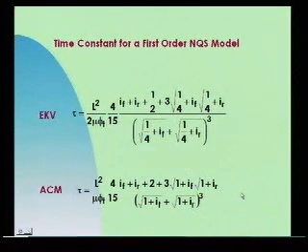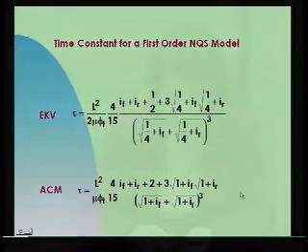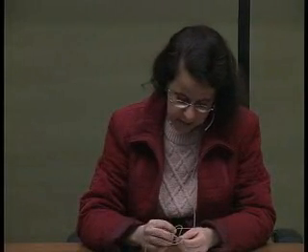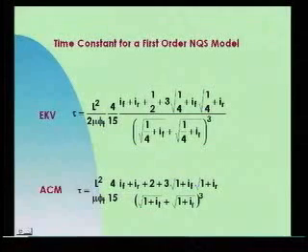In the next class, after talking about short channel effects, I will show you some circuits. Some we will analyze, for others we will design the circuits, and we will use one of these models. It does not matter which one because of their similarity. But for the circuits that should work in weak inversion, I will use the exponential asymptotic approach.